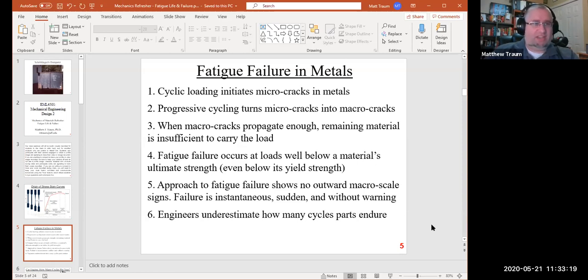The wings are very flexible, and so when you're in flight, they actually will oscillate a little bit. So that's a cyclic load on the wings of the airplane, right? And the other parts of the airplane have to undergo cyclic loading when they're in flight. Every time you land a plane, that's a cyclic load. Every time you take off, you put the various components through their maximum stress design points. And so airplanes are subject to an awful lot of cyclic loading.